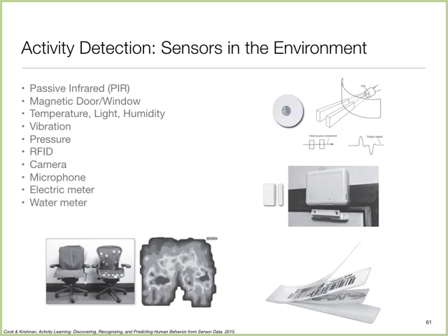The other thing is that many of these devices, when they turn on or off, cause a transient in the voltage. I'm sure you would have seen these things, like when a heavy duty load starts, the voltage may dip a little bit. But even if it doesn't, you will see signatures. Your laptop power supplies, for example, are so-called switching mode power supplies. So every time you connect your laptop to the outlet, there is a back injection of some AC frequencies. If you monitor the wideband spectrum on the voltage line of your home, you would see a rich array of signatures there, to the extent that you can identify that there is an Apple laptop there or stuff like that.